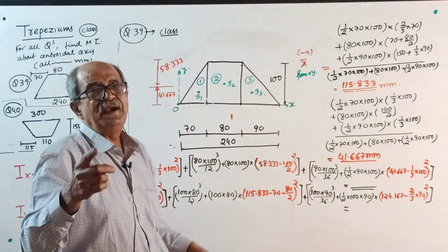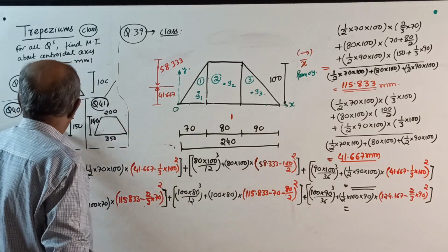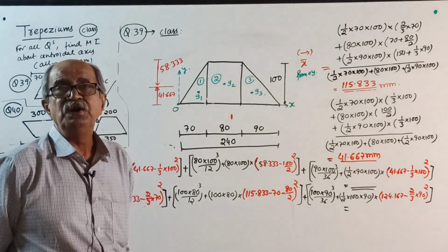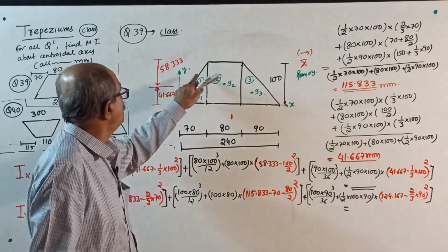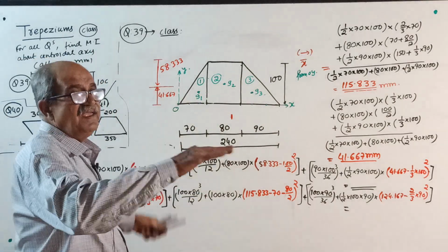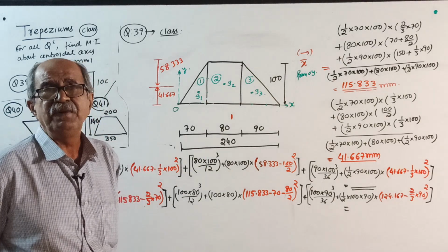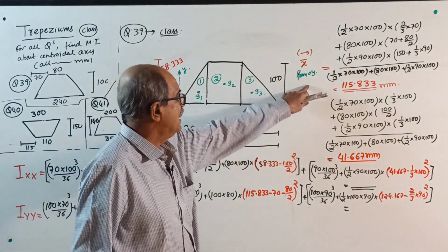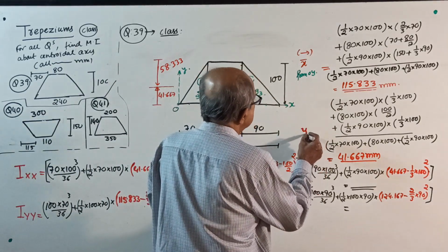See, one more thing. Now, the basic statements I will not write. You should write. Every question, 39, 40, 41, you have to write. Divide into 3 parts, that you have to write: 1, 2, 3. Take reference point O for OX and OY, axes OX, OY for locating centroid. Moment of inertia required about centroidal axis means IXX and IYY. So you have to locate XX and YY passing through centroid, capital G, in red color, and all that you write. Even the formula for x bar, y bar I will not write. Why should I waste my time? My time is precious for that matter.